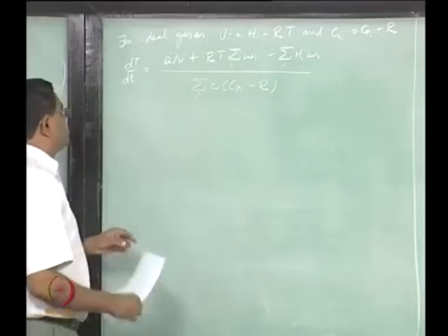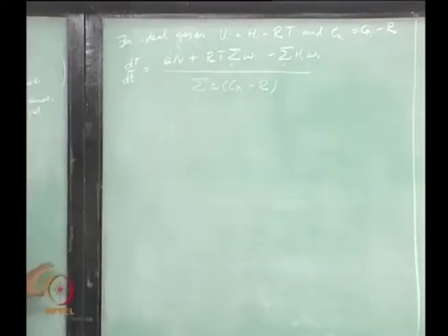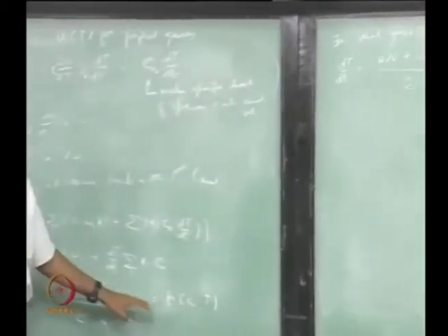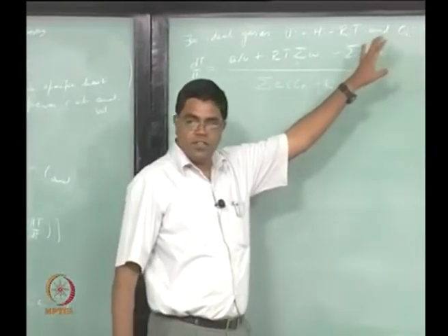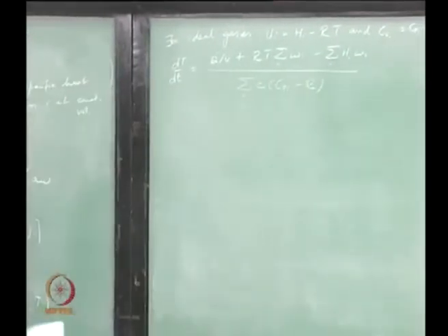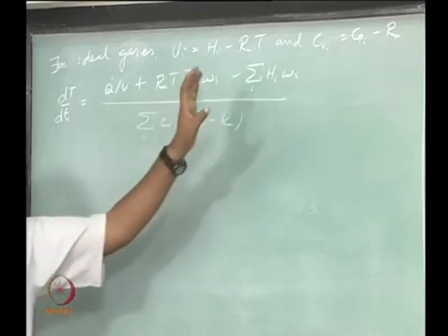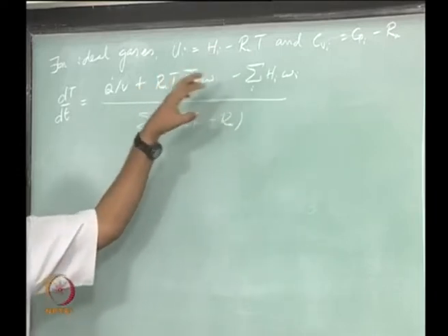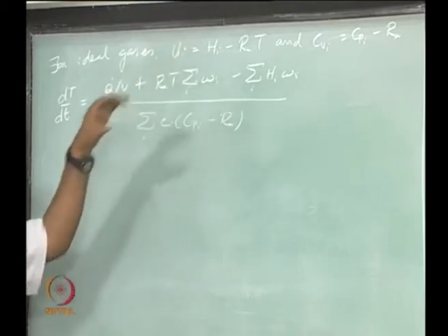The reason why we are actually having a universal gas constant show up here is because we are dealing with things on a molar basis. Okay, so you would have a specific gas constant only if you are using things on a mass basis, therefore this is appropriate. I would like to make a few comments. We will in the future look at these kinds of expressions or terms, but I want you not to get confused at that time.